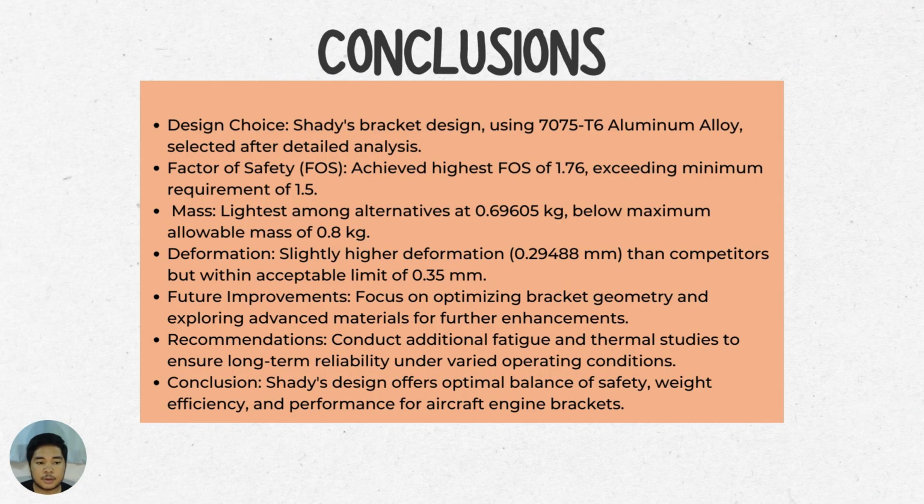In conclusion, the design choice is Eirshady's bracket design using 7075-T6 aluminum alloy. For the factor of safety, it achieves the highest factor of safety of 1.06, exceeding the minimum requirement of 1.5. Mass is the lightest among the alternatives at 0.69 kg, below the maximum allowable mass of 0.8 kg.